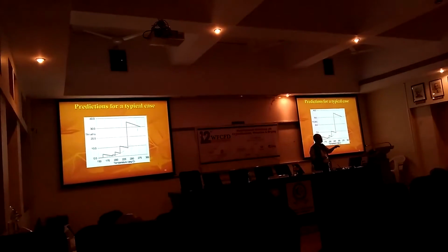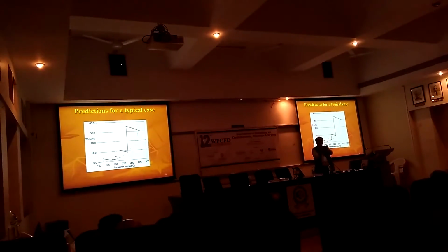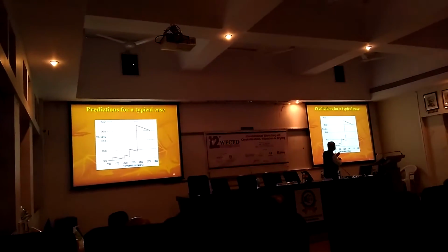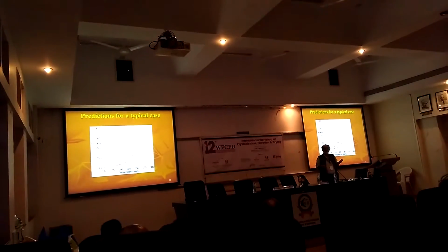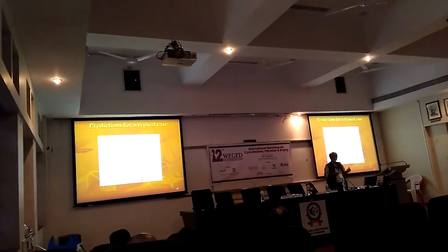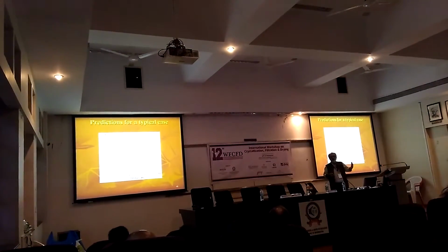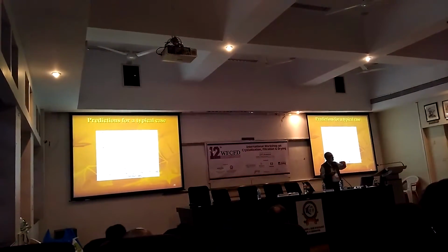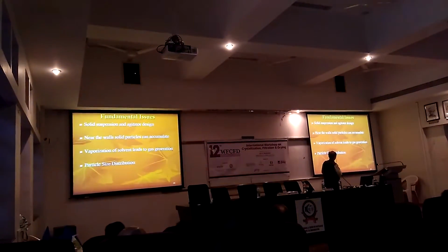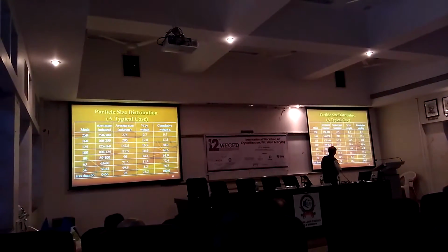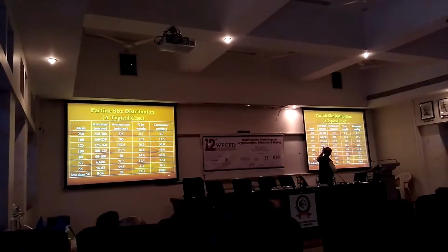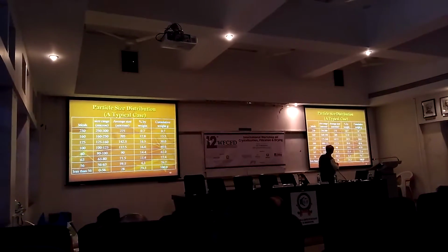The stage wise is important because this will allow you to operate in that metastable region. If I continuously keep on evaporating it and reach this particular level, I will not be in a position to get the required nucleation rate, required growth rate, because I am crossing that metastable zone width limit, as a result of which spontaneous nucleation is expected. So this is that case which I showed you about, that this is the way it is operated. You can get a particle size distribution.